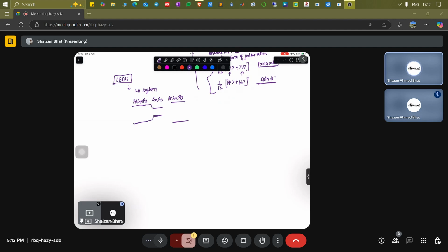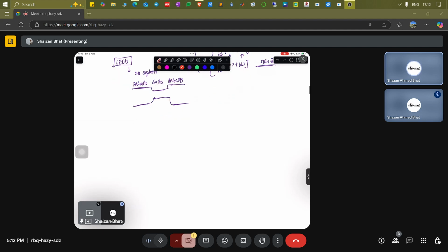So when you connect these particular systems, you get a system like this, wherein now if you inject electrons into, let's say for example, gallium arsenide, because of discretization of energy levels for the electron and the hole, you will get electron hole pair recombination, and it's going to emit photons. So now the photons will come out. That is basically in the visible region, and you can tune those regions as well. Accordingly, you can get a photon of red, green, blue, and accordingly you can have applications in display screens.